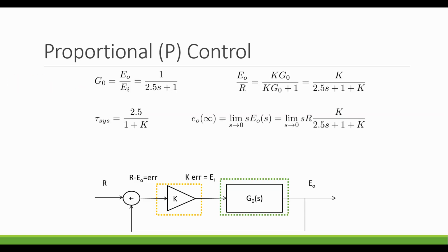And to see what the steady state value or final value is going to be, we can use the final value theorem on this. So we have a stable system here. Our s is going to be in the left half plane. The one pole is in the left half plane for our system. So we're okay on that front, so we can apply the final value theorem.